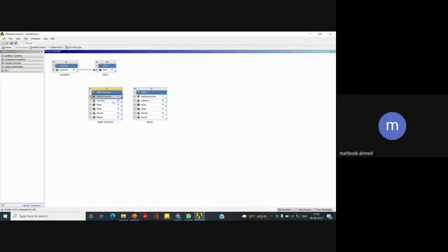In ANSYS, it gives you three options to have the geometry. You can right click on the geometry part, and you will see the options. So it has New SpaceClaim Geometry, DesignModeler Geometry, and Import Geometry.